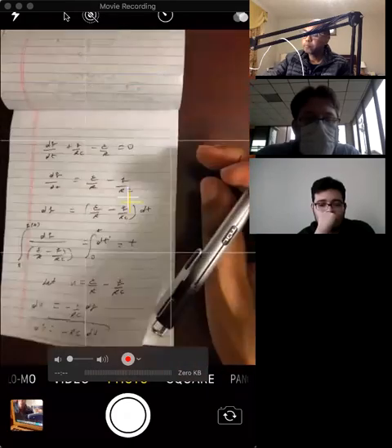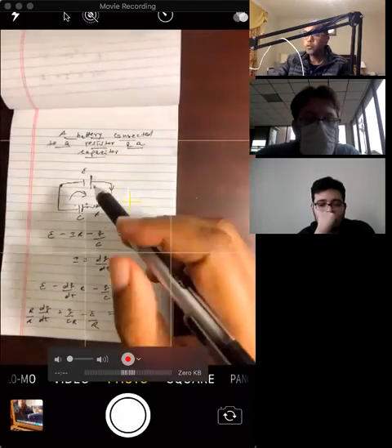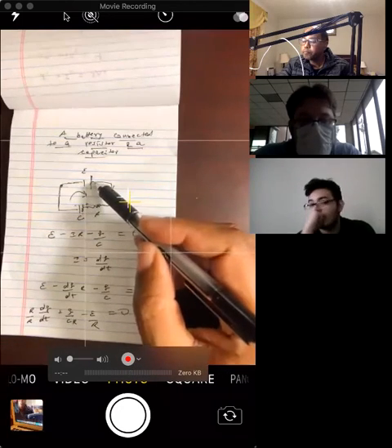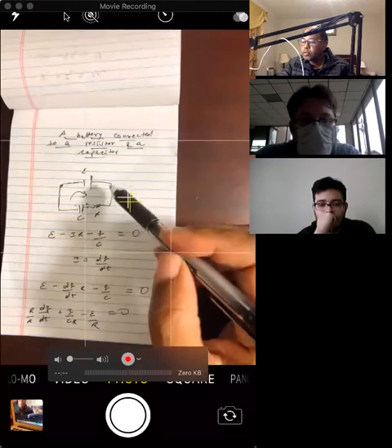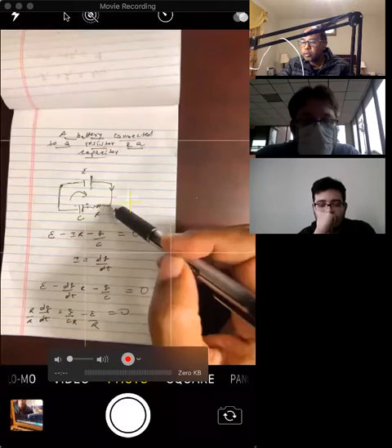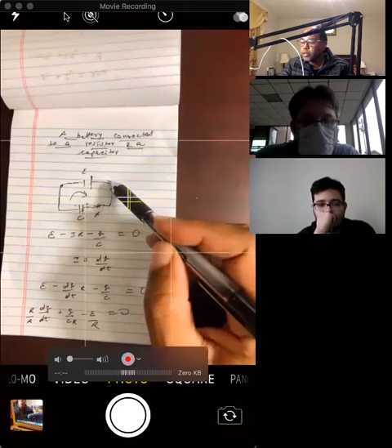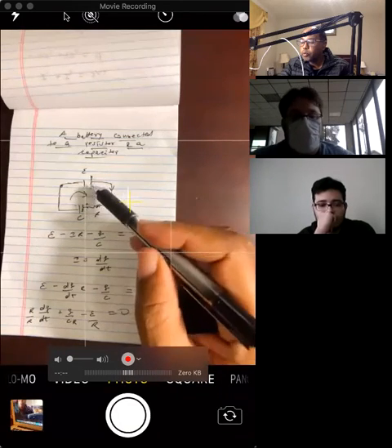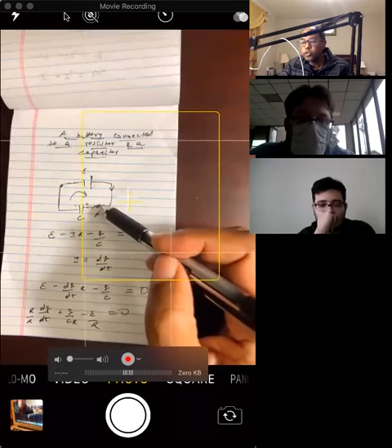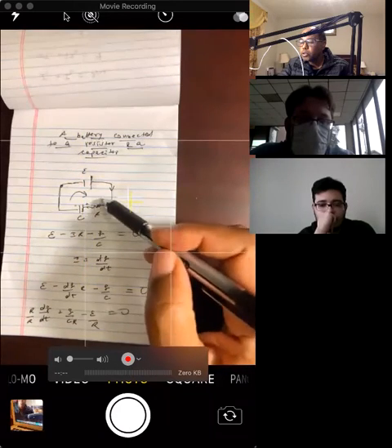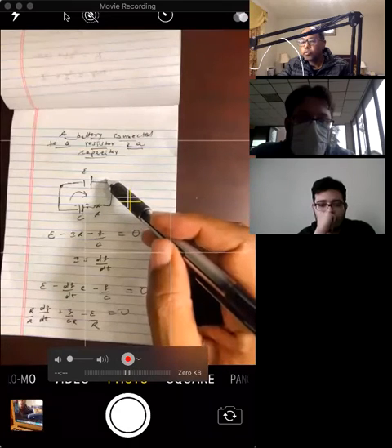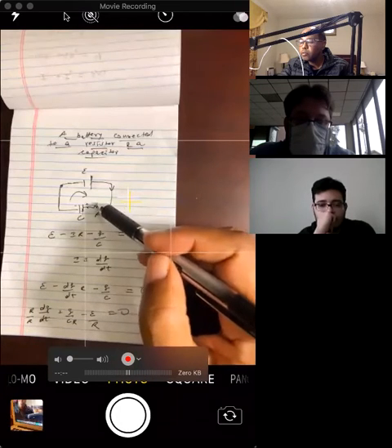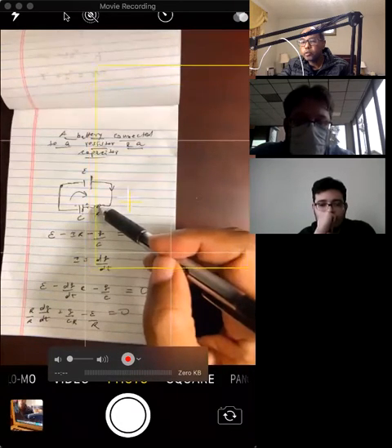So we have a battery connected to a capacitor and a resistor. What happens is, you see this starts from a 0 charge. So this battery is going to charge it. But it starts with the maximum current at t equals 0. You have no potential difference over here. The entire potential difference is across this resistor, which is E over R. So this circuit starts with a current of E over R, and then eventually all the potential difference goes to this one, which is Q over C, and there is no potential difference at the resistor eventually. Okay, so that's what's happening.